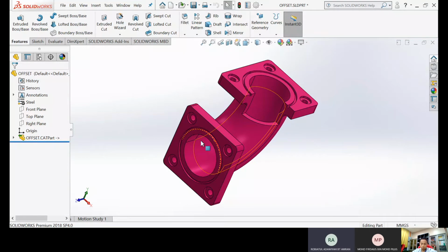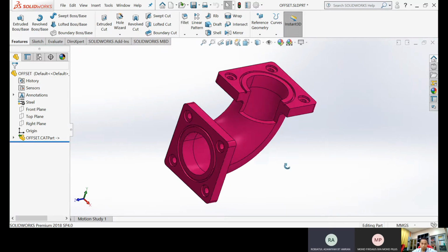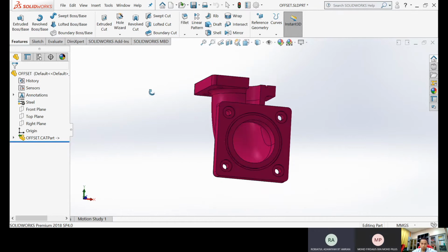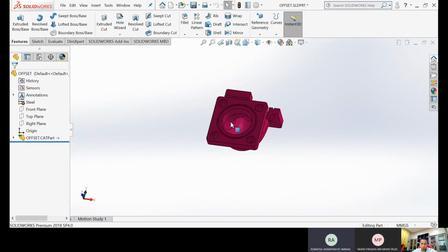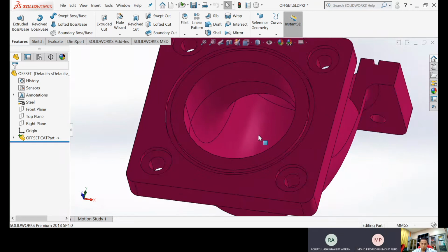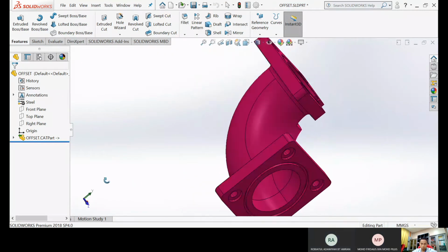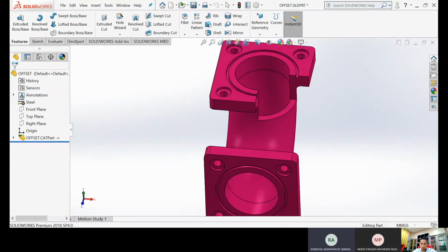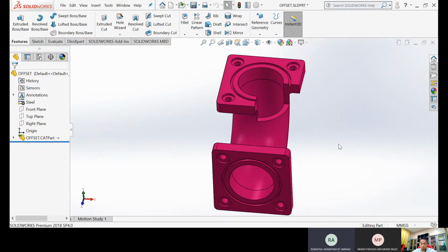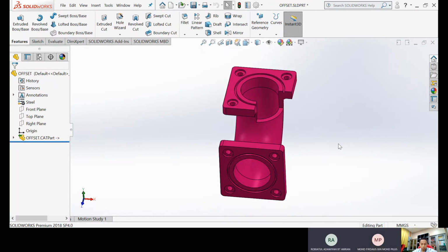Next, use the simplification, which means reducing the STL edit size to remove unnecessary information to get a smaller size. Smoothing is the section that decides whether simplification is needed or otherwise. Rotate the part to get a good view. Use the global slider to remove some of the frequency that was added by the scanning process. Use the slide bar to the boundary to smooth out the boundary as much as possible. Use the local smoothness if there is a hole or bad geometry. Just manually cut out the unnecessary information around it. Then deselect that option and save the file.